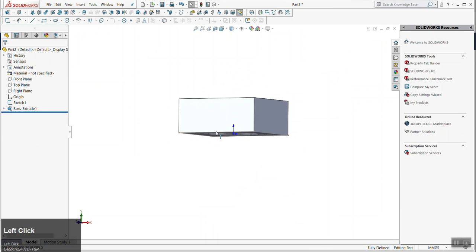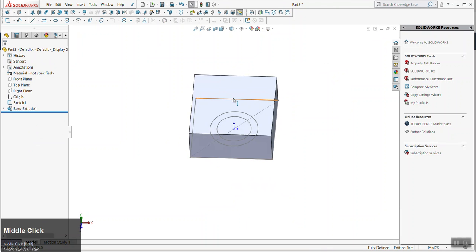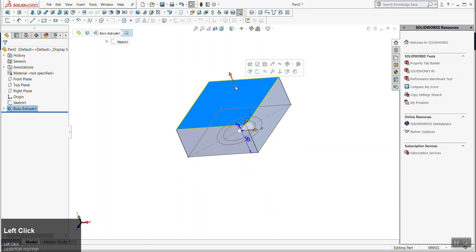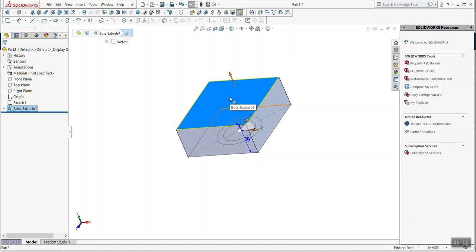So there we go. That's a 50 millimeter extrude. Now I'm going to click on this face. So instead of creating a sketch on a plane, in this instance, I'm creating it on a face. We can get into deeper conversations about this, but essentially, anytime you select something, in this case this face, if I build a feature on it, and this face were to disappear, if I were to remove this feature, it would leave the feature that was based off of it hanging, okay?